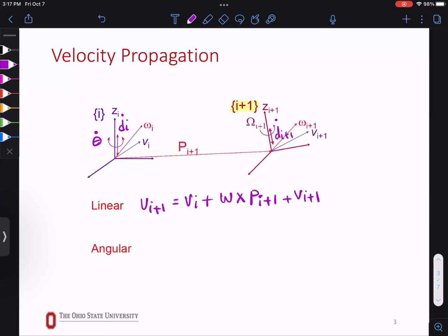If it was a rotary joint and you wanted to know if there was a linear velocity in that same frame from the angular velocity of itself, would there be one or not? No. Why? Because there is no distance, right? So at its own frame, there is no linear velocity because of its own angular velocity. So you're done. It doesn't matter what robot I did.